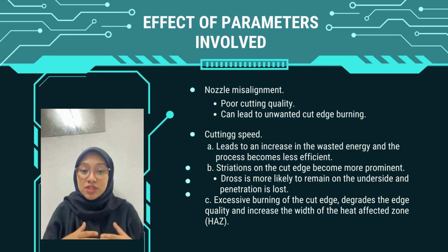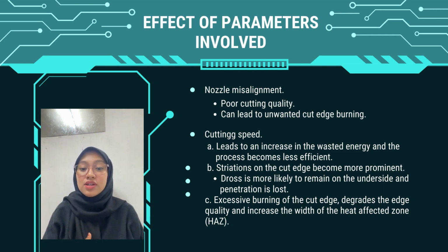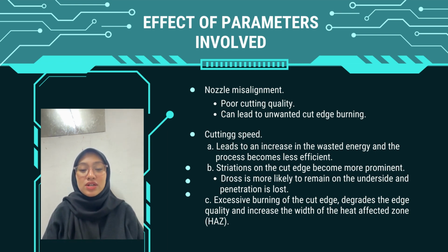The speed must be reduced when cutting sharp corners with a corresponding reduction in beam power to avoid burning. So the last effect is the effect of focal position. The focal position has to be controlled in order to ensure optimum cutting performance. Differences in material thickness may also require focus alteration and variation in laser beam shape.